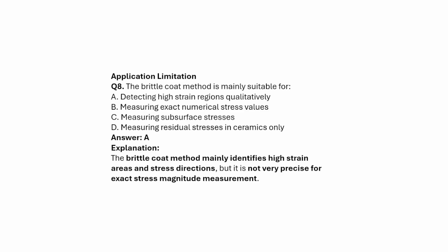The brittle coating method is mainly suited for A, detecting the high strain regions qualitatively, B, measuring the exact numerical stress value, C, measuring the subsurface stresses, D, measuring the residual stresses in the ceramics only. Option will be A. So the brittle coating method mainly identifies the high strain areas and stress concentration, but it is not very precise for the exact stress magnitude measurement.